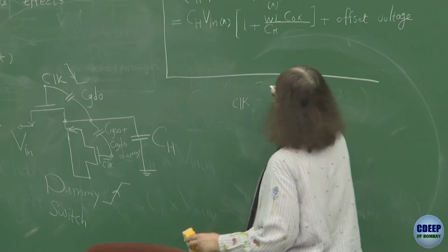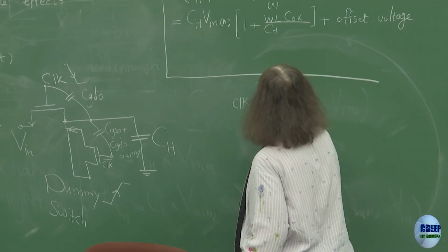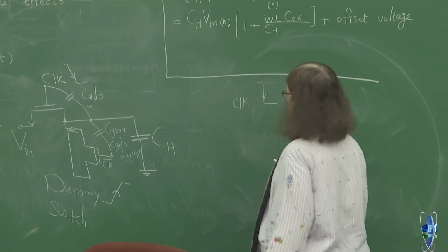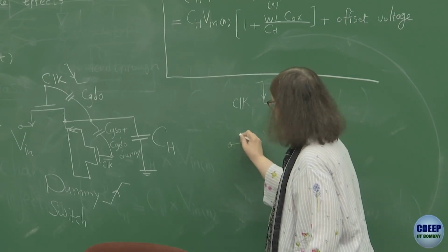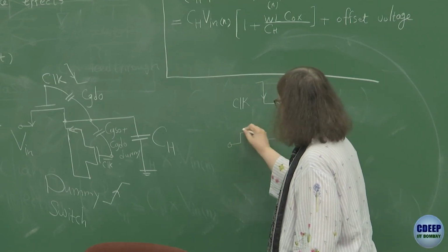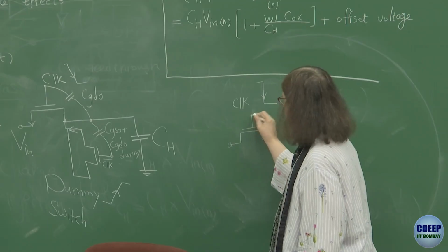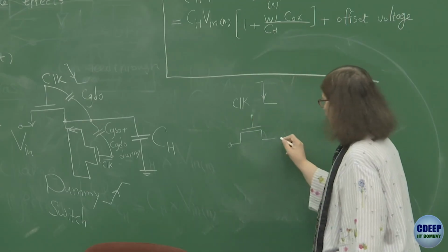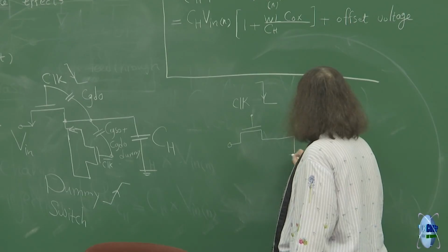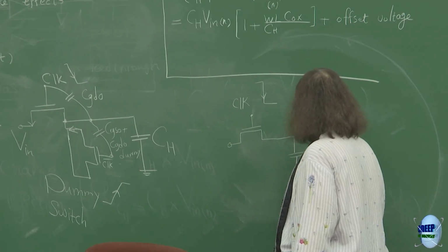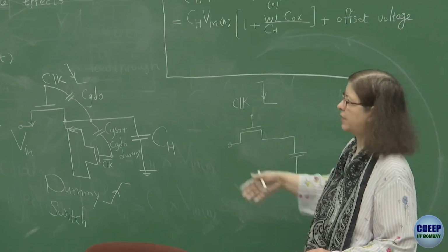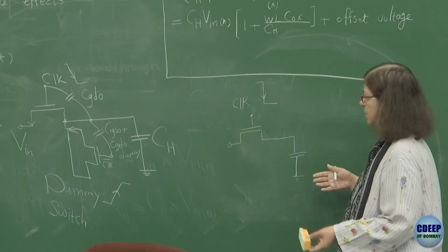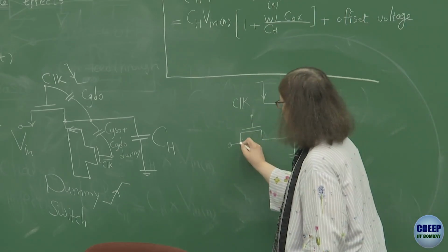Let's just consider both. Right now, for example, falling edge. In fact, clock feedthrough, when we look, we should look at both of them and see which one really, and what is the effect of each one of them on the circuit. Because when the transistor turns on, clock feedthrough still will go away, as I showed you, and it will settle. When transistor turns off, so this clock feedthrough needs to be taken care.